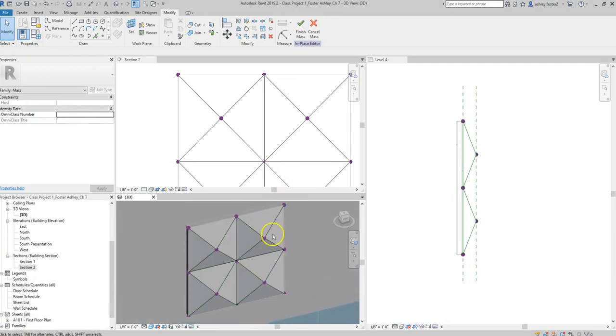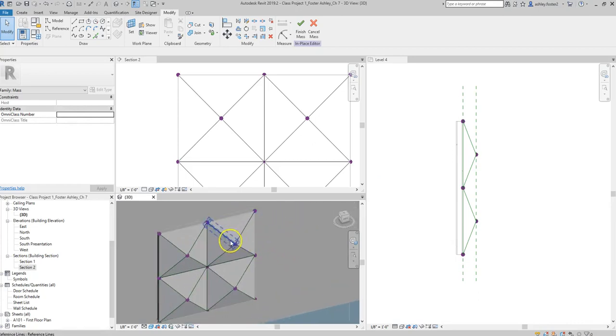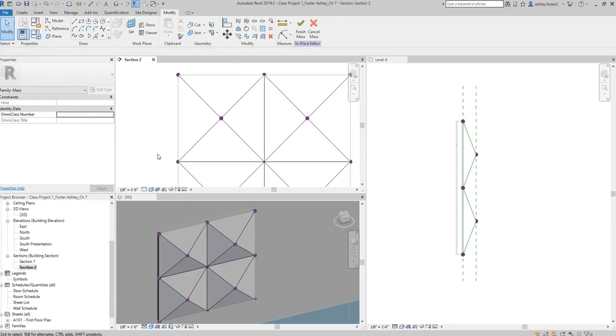In other times when I've created this wall, there is one troubleshooting issue that you may run across where the plane does not equally line up with the other two, or it shoots the wall off into a different direction. In that case, just select the triangle that's there using the tab key if you need to, and then you can go to Edit Profile. In those cases, it's usually because it's wrong that that option will be available for you. And then just drag your pink lines into the shape that you need it to be, and then click OK. And that should fix that issue for you.